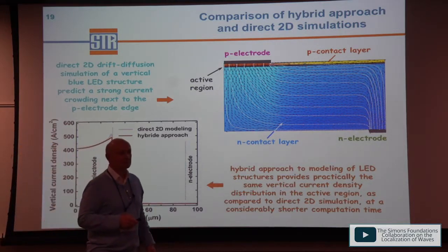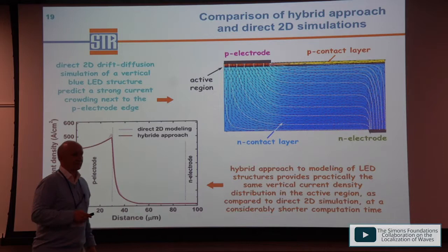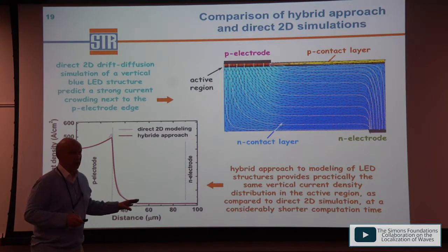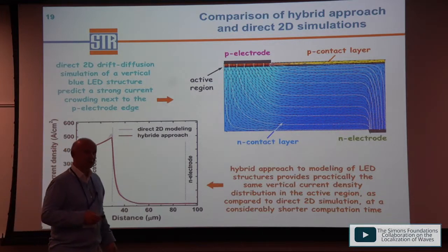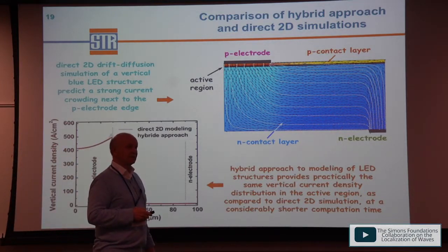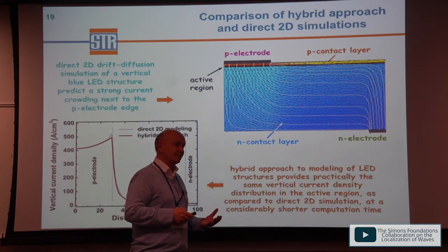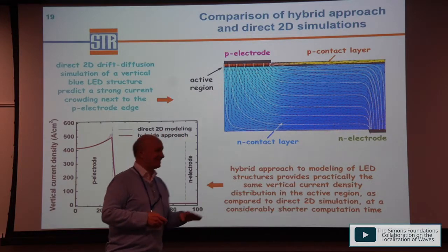Are these finite differences? Finite volumes. Okay, so in principle, you would have an adaptive mesh. Yes, it's better if you use non-structured grids for simulations. With non-structured, non-equal grids, then you probably don't even need the hybrid approach, because you can use a very fine grid for your middle part and a very coarse grid elsewhere. Let me show the grid a little bit later.